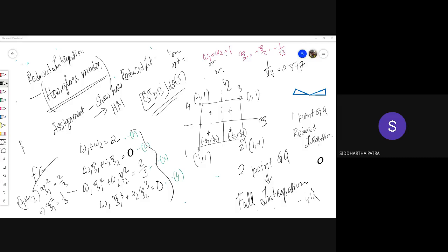The first thing, which I have perhaps not been able to make clear, is that the goal is never to get an exact solution. The goal is to get an approximate solution, but even an approximate method needs to be benchmarked so that in the situations where it is desired to give you exact solution, it should give you exact solution. You can use a single point Gauss quadrature for a 4-noded element, and there is no way a single point Gauss quadrature can give you exact solution for a 4-noded quad element, because we have already established that B transpose DB is going to be quadratic in xi and eta, even if the physical shape is a parallelogram.